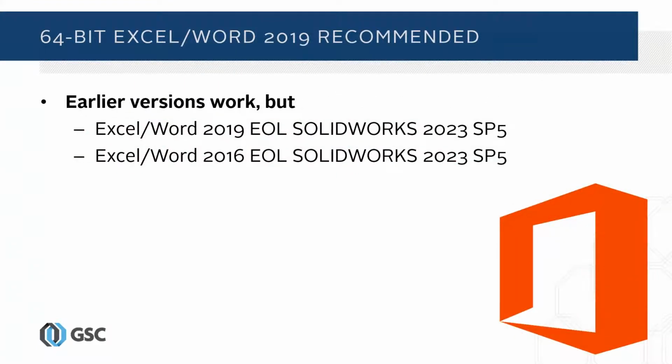What sometimes people forget is that SolidWorks also interacts with elements of Microsoft Office, in particular Excel and Word, depending on what you're doing in SolidWorks for reports and what have you. But certainly, design tables use Excel and rely on that. So you have to keep up with your Microsoft Office too. Again, nothing too drastic, but some people really stay on old versions of Office. So if you're on Office 2016 or 2019, even between those two, you have a year left before that's going to be unsupported.